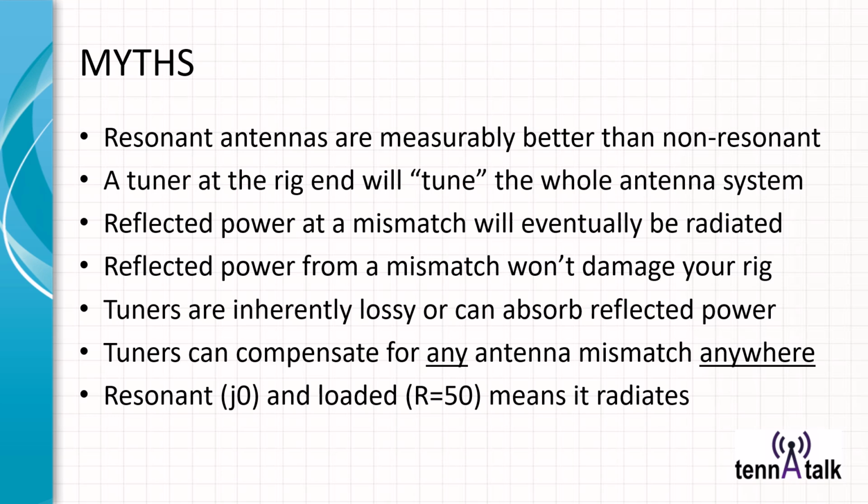Well, unless you have a modern rig. The older rigs did not have what's called a foldback circuit that pulls back on their RF power when it sees a high SWR to protect its final amplifier components. And you could blow out a final amplifier. People have done it many times.